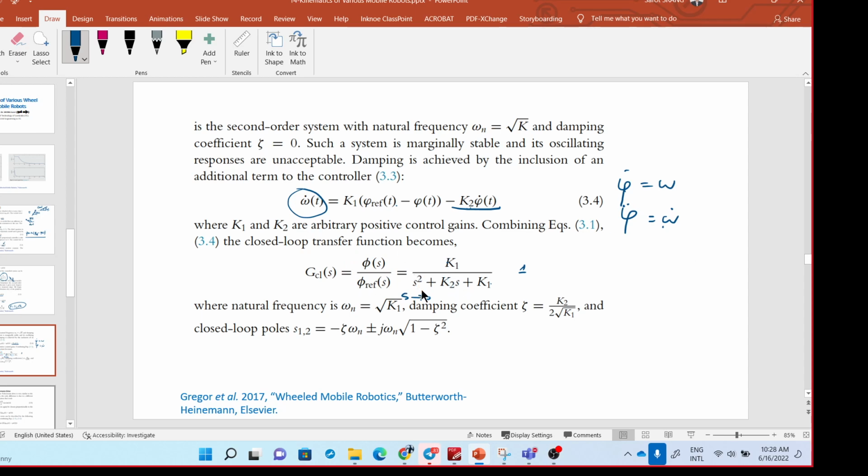And now we have second order, so the behavior of second order, like natural frequency, damping ratio, relates to the performance, like how many percent overshoot, what is the rise time, settling time, something like that. So we can choose the right damping ratio and natural frequency omega n, according to our desire.